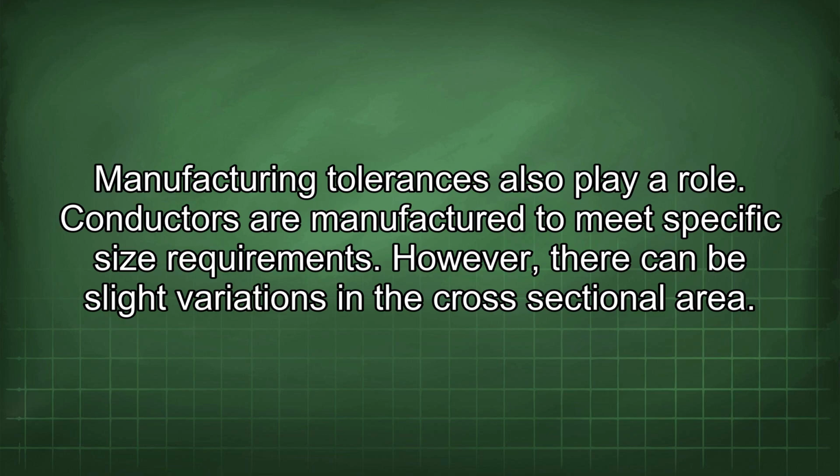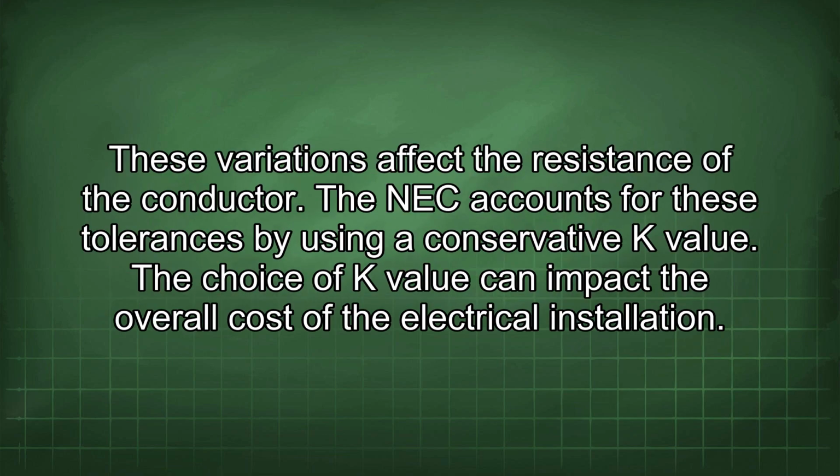Conductors are manufactured to meet specific size requirements. However, there can be slight variations in the cross-sectional area. These variations affect the resistance of the conductor. The NEC accounts for these tolerances by using a conservative K value.